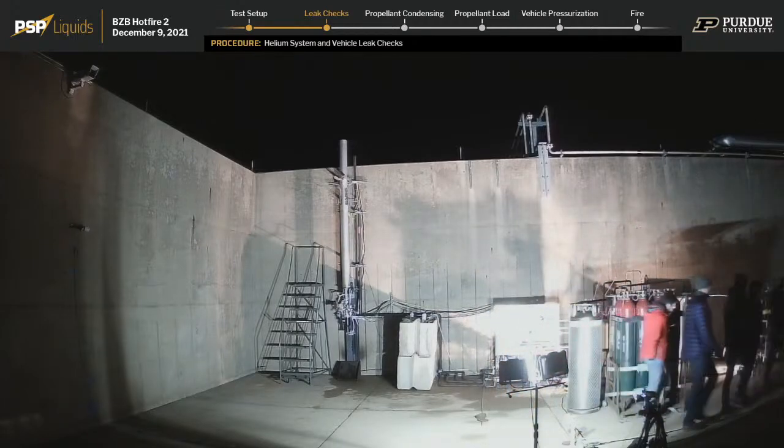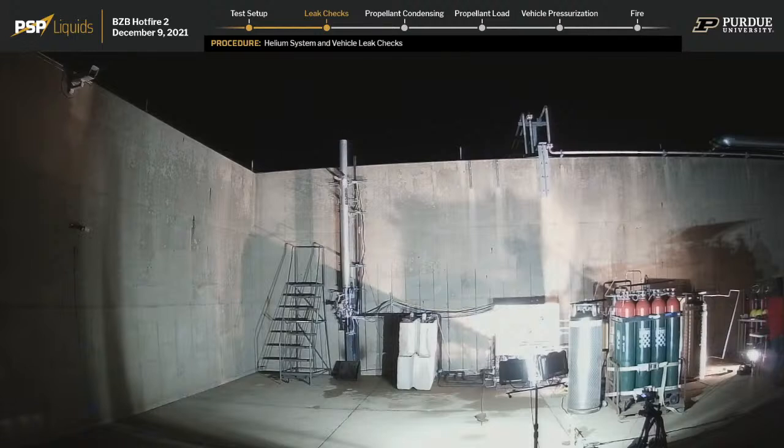So, I think there's a great answer in chat already, but just to reiterate, what we do to figure out our leak rates is we pressurize a certain part of the rocket and hold it at a certain pressure, and then we close off that volume to the rest of the system. By looking at the pressure data over time, we can figure out how much the pressure drops over a known amount of time, such as a 5 minute test. And when you know how much that pressure has dropped in a given amount of time, and you know the volume of the section you closed off, you can figure out how much has leaked.